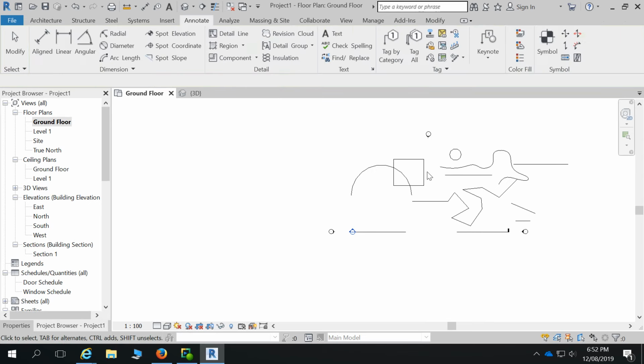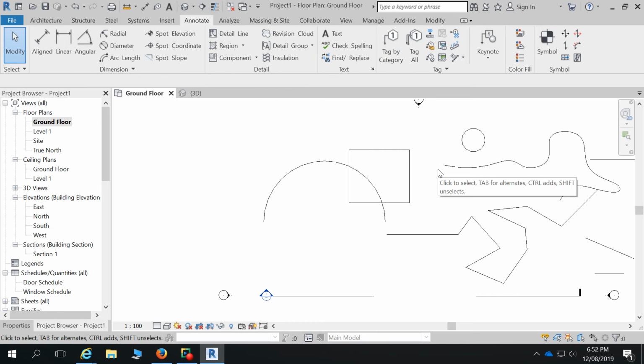So it's a very handy tool for when we can bring in CAD drawings. We can bring in other 2D drawings, and we can pick lines as walls. When we start drawing in 3D, we'll do an exercise that is that. We'll bring in a 2D plan, and we'll click on the lines around the outside, and they'll become 3D building elements. So it's a really quick way, rather than having to pick the end points and trace around, we're literally just hitting it, and it follows the whole wall length in a 3D sense.